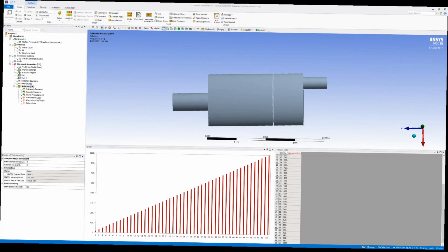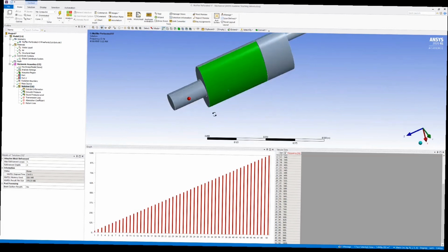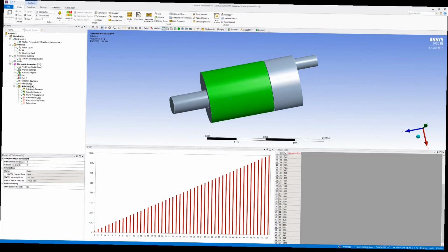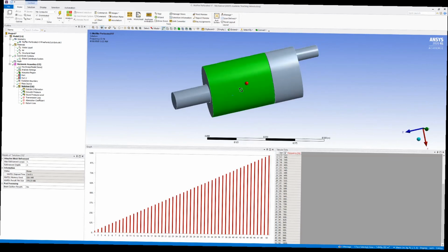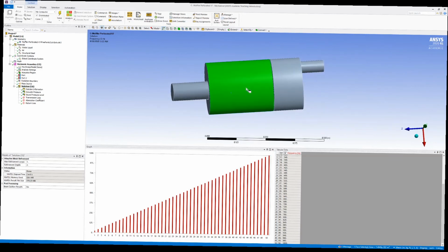Like I said, to improve the design, you can add foam and have a porous material region with a porosity coefficient that you'd use. You could add additional baffling with multiple outlet ports with even more baffling to see if that helps your transmission loss in your frequency band range. You can also use different tube paths, different tube bends at the inlet outlets to further attenuate noise.